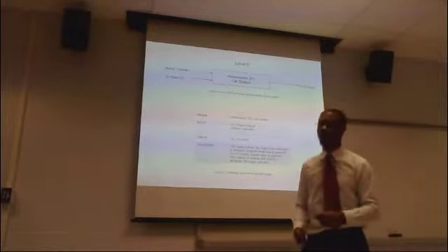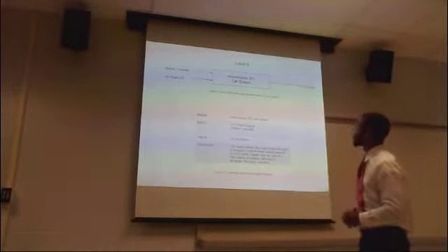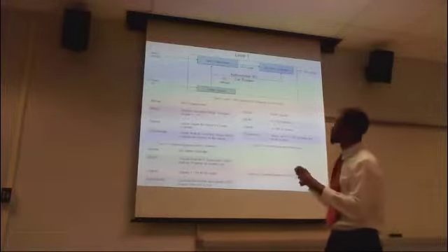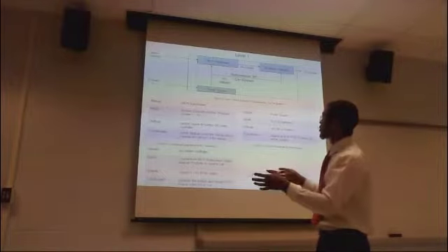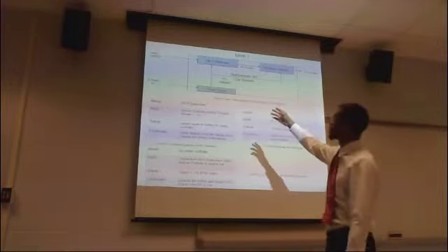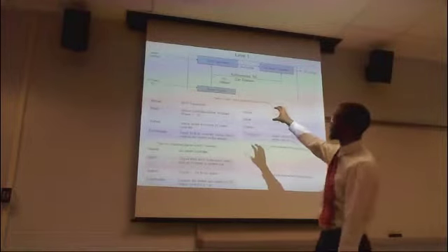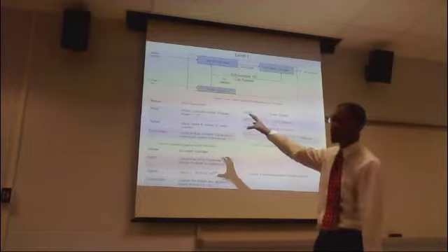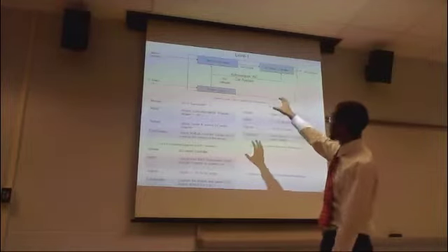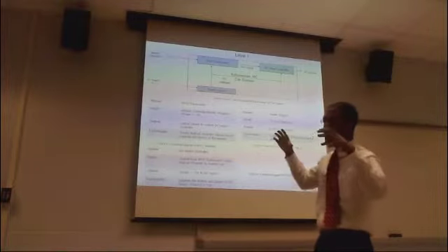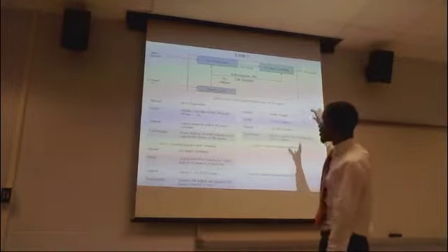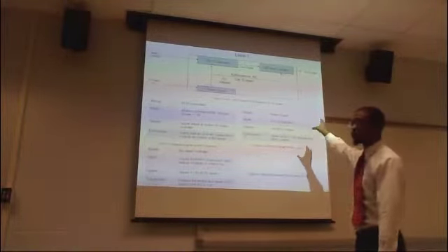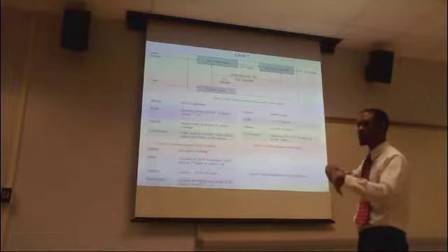When you go into the level 1 block diagram, you're going to look at a more in-depth view of what's going on inside the system. This shows that the motion controller is connected to the Wi-Fi transceiver, which sends a signal to the DC motor controller, which is powered by our power supply, sending up to 5 volts DC into each of these units to power them, which in total will send an output signal to our 6-volt DC motors and control them in the way that we want them to be controlled.